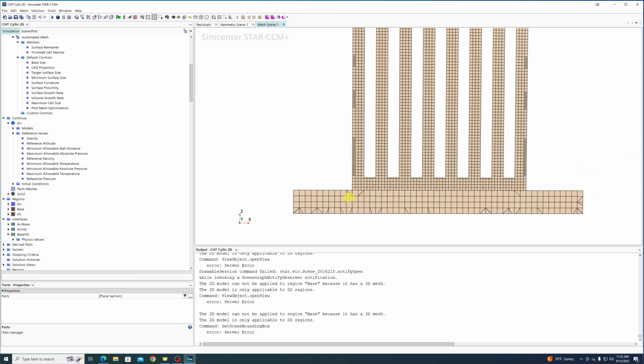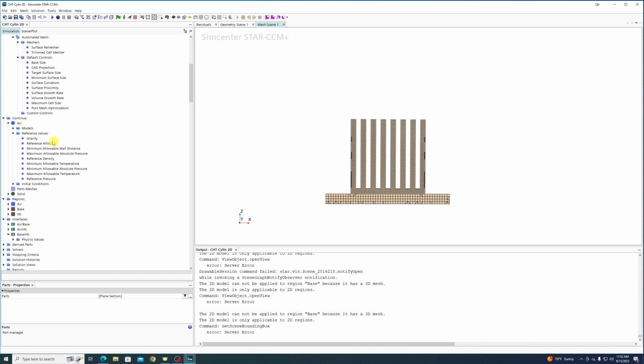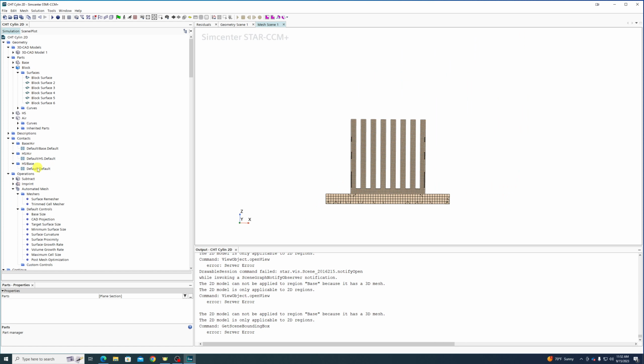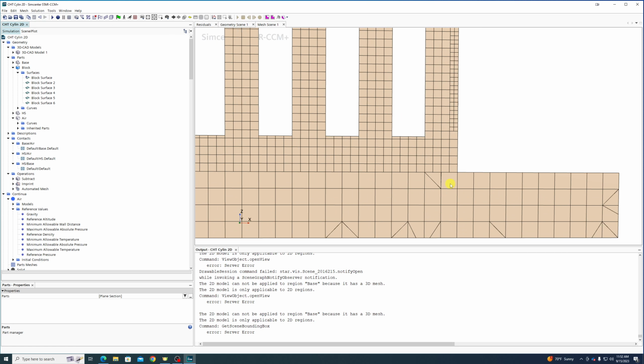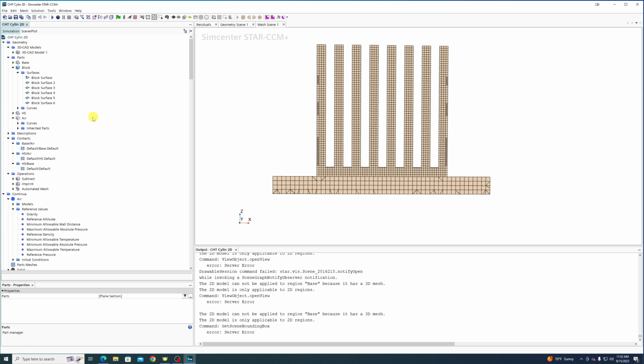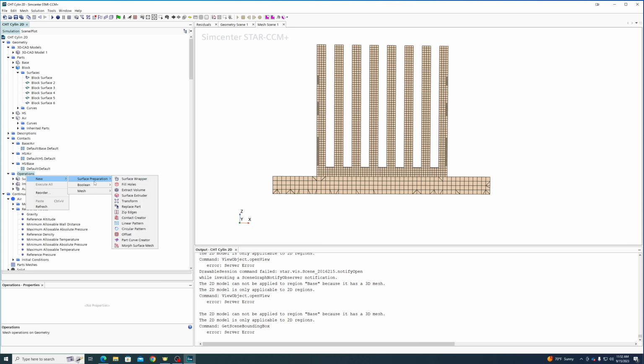That's fine. We're not being super duper picky about this. That's fine. I would like to maybe see a slightly... Well, no, this is as good as it gets. This is a 2-to-1 cell size transition, which is as good as it gets for the purposes of really anything with a trim cell mesh.